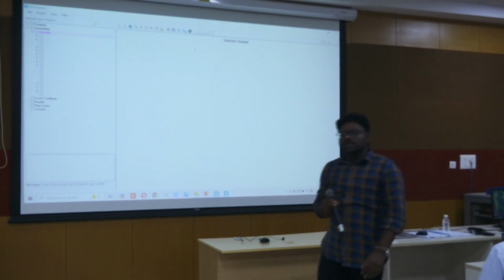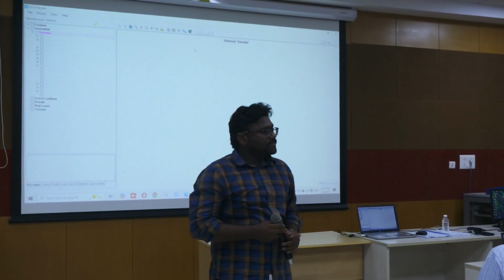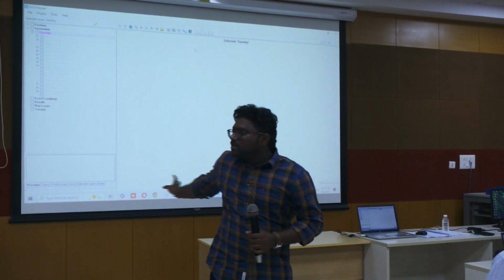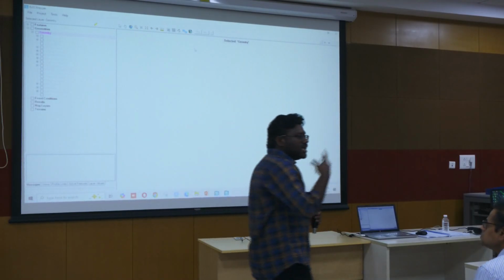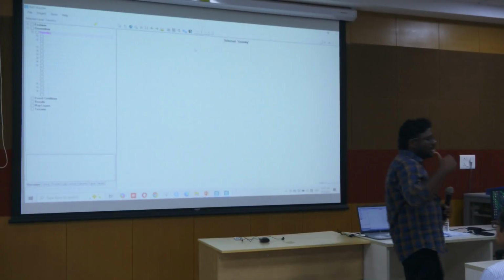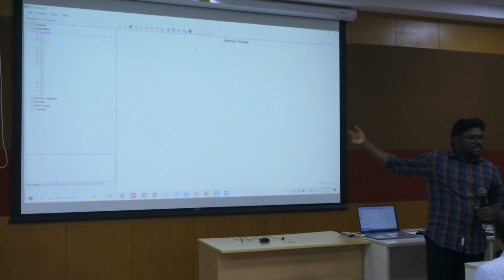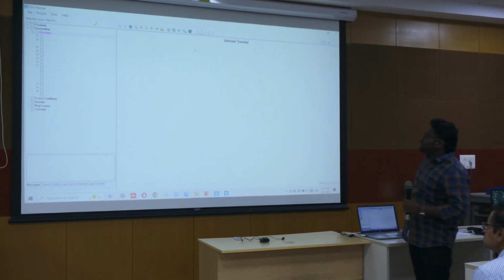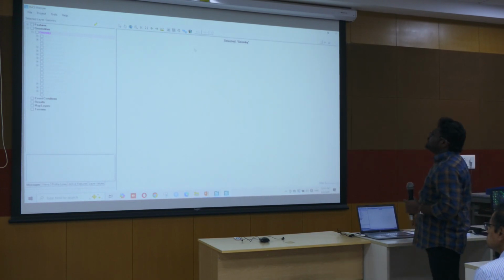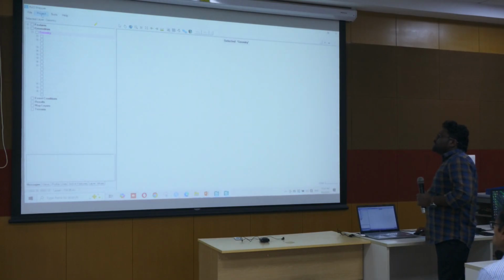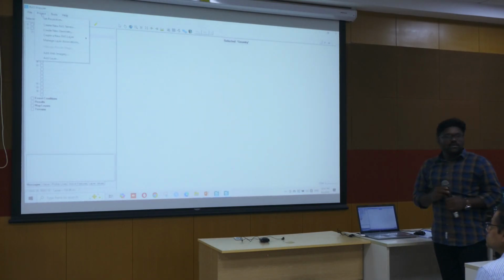All of you reach here? Click RAS Mapper. It is like our GIS layer. First, to see all our rasters, we need to set projections. We need to assign coordinate systems to this. So the first step is setting projections. For that, go to Project.